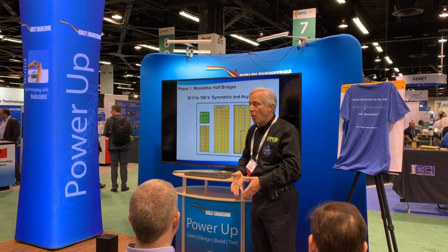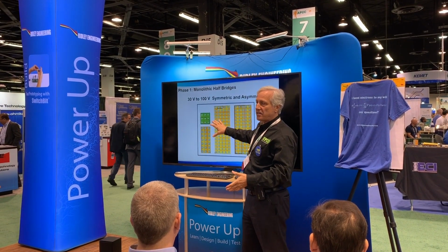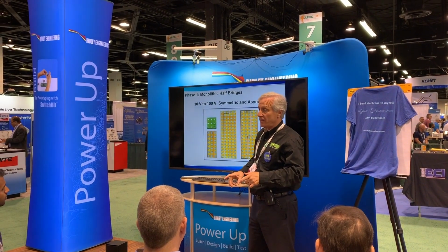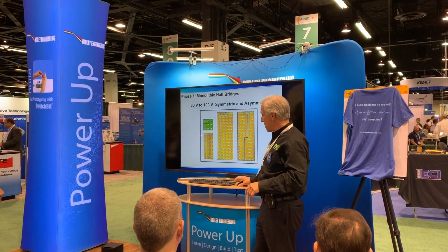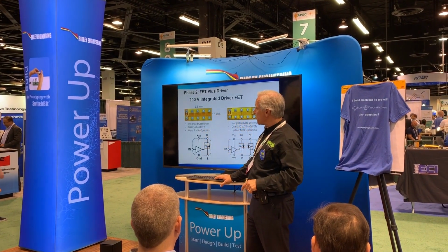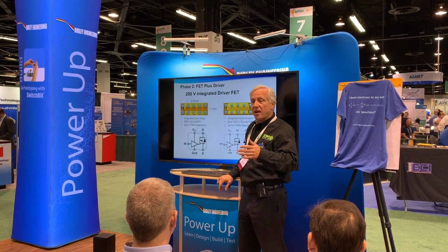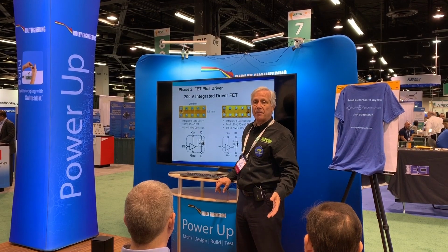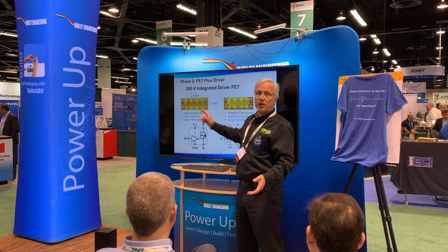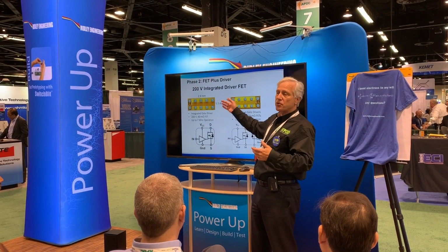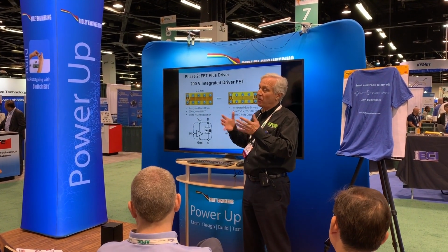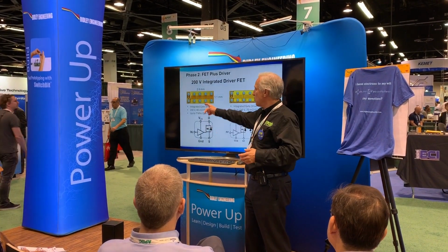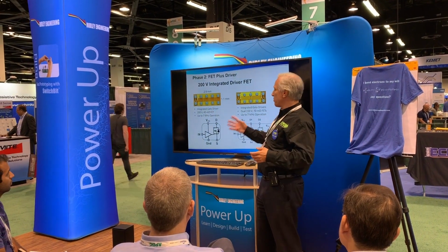So step 1, gotta get these power devices together. Can't do that in silicon, not above a certain really low voltage, like 10, 12 volts. So this is big. Step 2: every one of our GaN devices has a driver in front of it, so let's stick the driver on there too. So in step 2, we introduced these parts a year ago, where you put the driver on the same chip, in GaN, with the FET. And here's 2 of them.